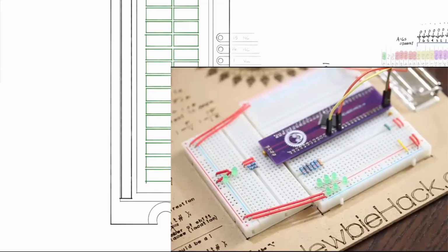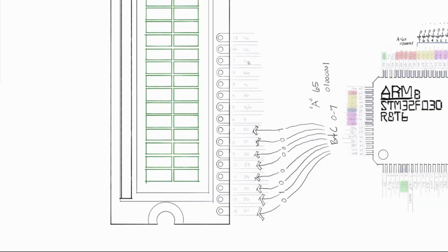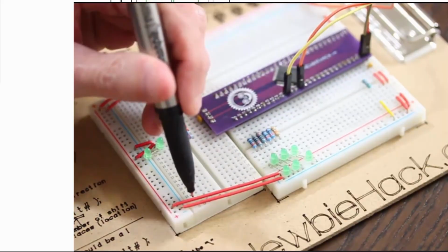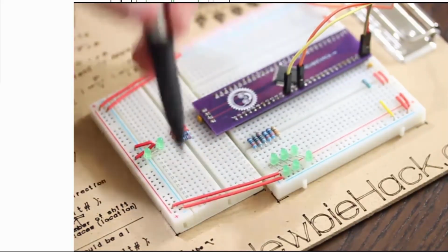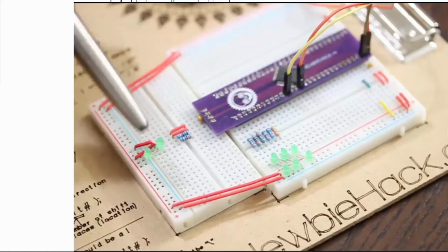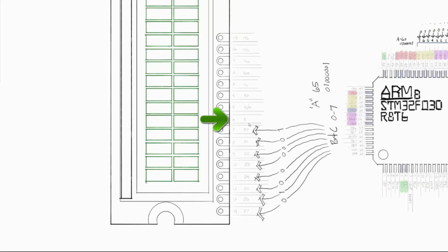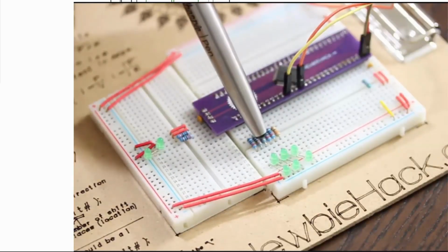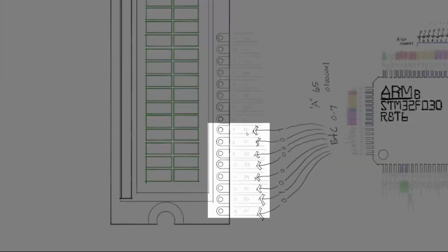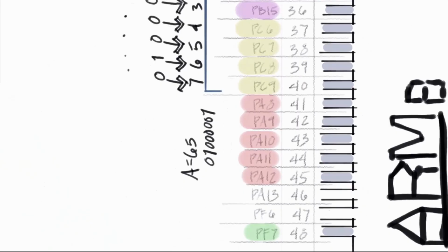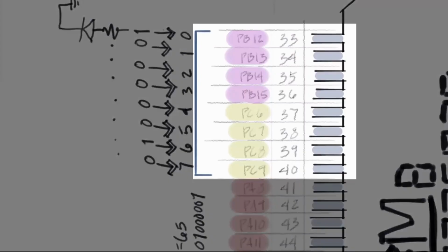I plan on putting the LCD along this area here, about 14 pins. On the breadboard I have, including these two LEDs, 14 and 15. So I do have enough pins here. So the register select could be the first one. The read write would be the next LED. Enable would be the LED that's on this pin here. And then after that, we can have these pins from D0 to D7 along this side here. We're using the pins number 33 through 40.